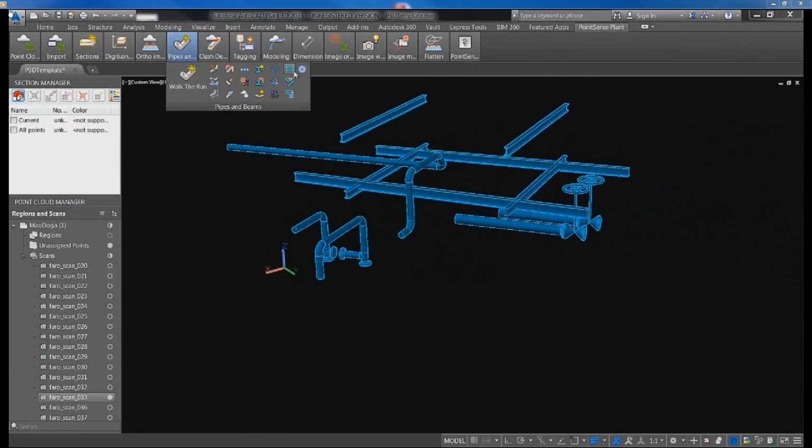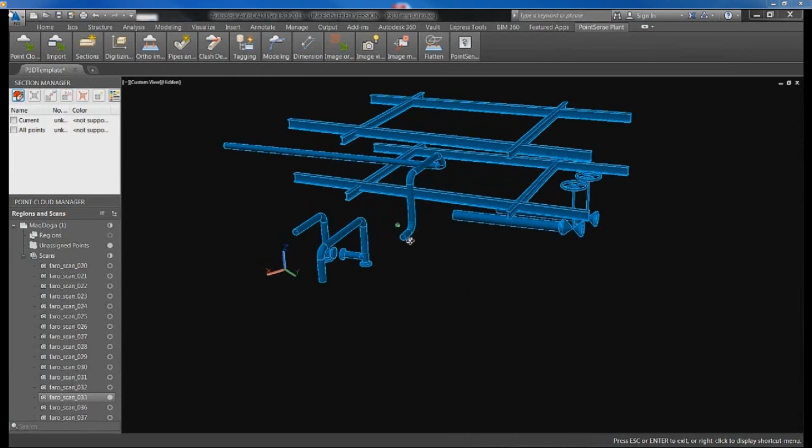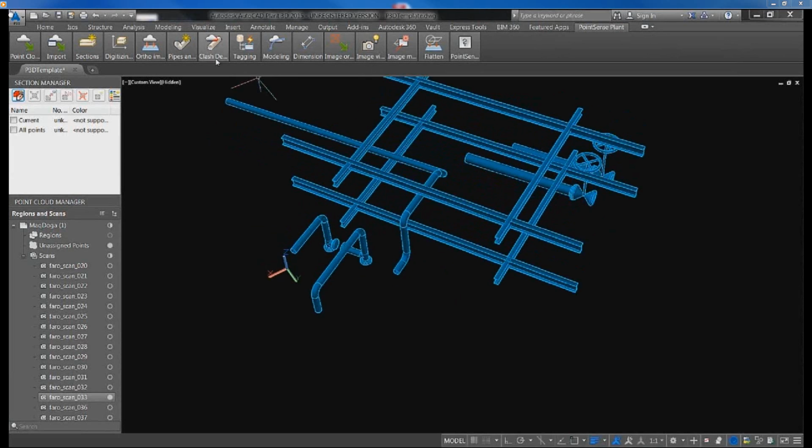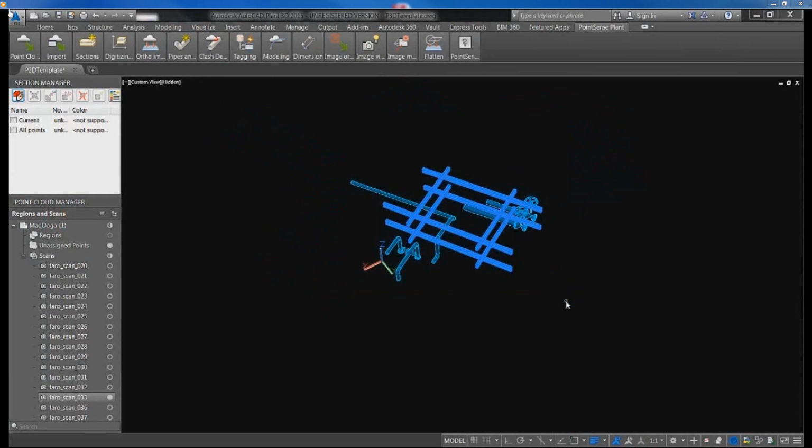Now the other thing I do here, and this is just to show people if you're having an issue where you don't see the steel very well, or it's just a nightmare to see in the data, you can actually take these pieces, and I did a copy selection and arrayed it up to the top row of the grid. What we're going to do from here is take those new pieces, which definitely aren't accurate because we didn't even fit it off cloud data, and then apply it to the grid using applied constraints. So it's a nice way to get pieces of steel in that you couldn't even detect out of the data. So here I choose all the pieces.